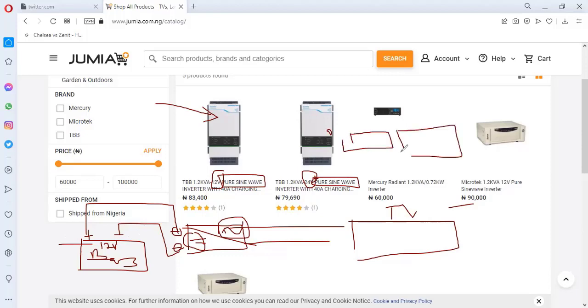And these 2 batteries, you are going to connect in series. Positive, negative, positive, negative. To connect in series, you connect the negative terminal to the positive terminal on the battery. Then you have the output negative and the output positive. Let us assume this is the inverter, and you have the DC input voltage terminal of the inverter. You now connect the positive to the positive. The negative, I'm going to jump here to show the wire is not touching, you connect it to the negative. This is the only instance where this inverter will work.